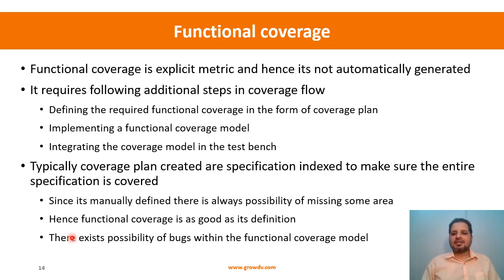As we talked about challenges associated with code coverage, like exclusion management, for example, similarly, these are some of the challenges associated with functional coverage as well. Nothing is perfect. We have to utilize multiple things and do a sort of checking of one thing based on another. That's the concept that we have talked about, like the reference model concept. The reference model concept is not limited only to the implementation of a scoreboard. In verification, you always tend to validate: okay, this component is saying this thing, that component is saying something else. Are both of them the same, right?